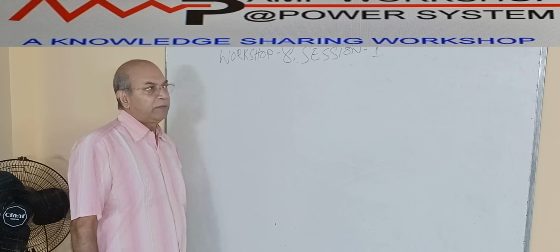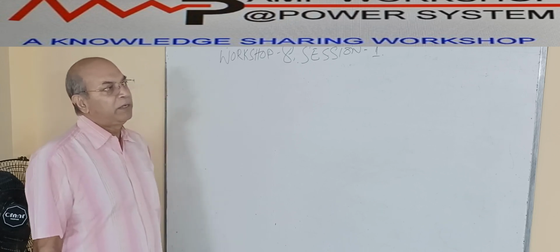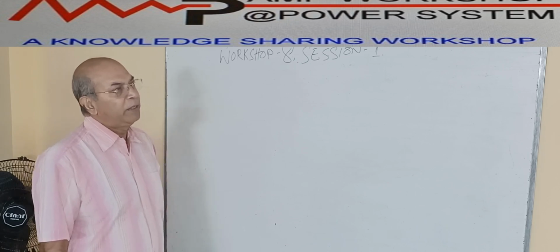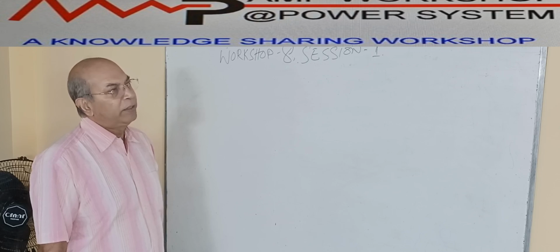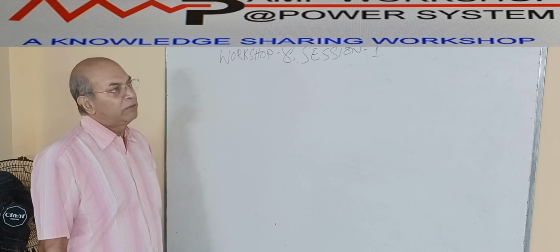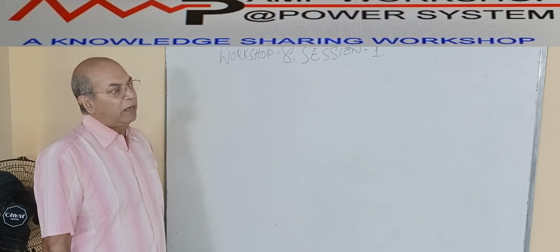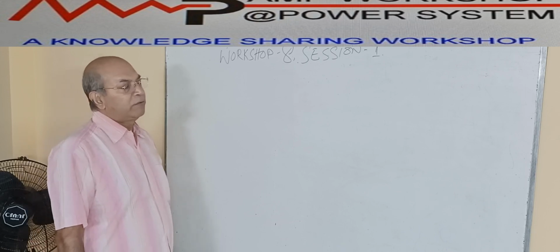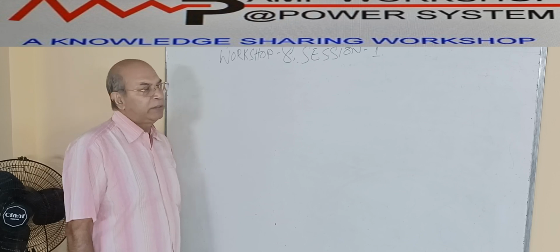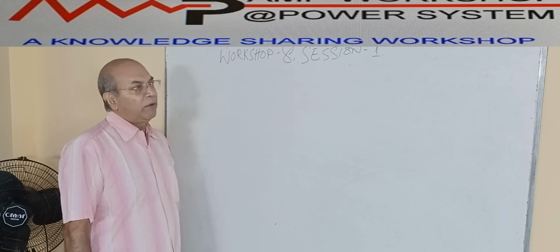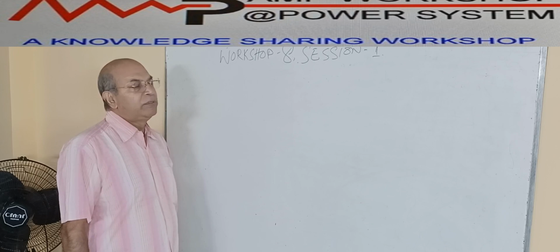So we will first discuss the various layouts for the medium voltage switchgear up to 33 kV, and then onward we will go up to 800 kV. The difference between these various voltage level switchgears is mainly their arrangement, various power component requirements, and how the components are connected to each other, which we will discuss in detail. And that is one way to classify the switchgears.